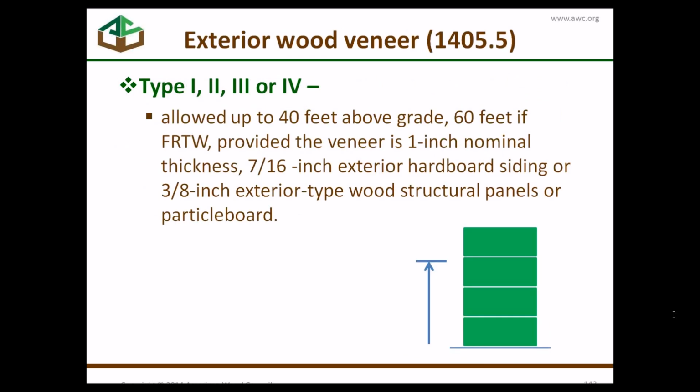Wood used as an exterior wood veneer has a height limit. There's an exception for fire retardant treated wood. This is a similar height limit for combustible exterior wall coverings back in 1406.